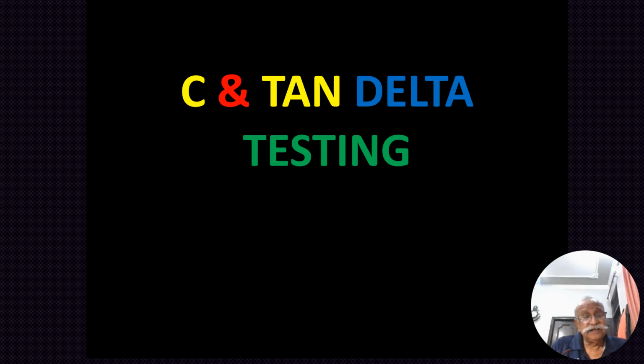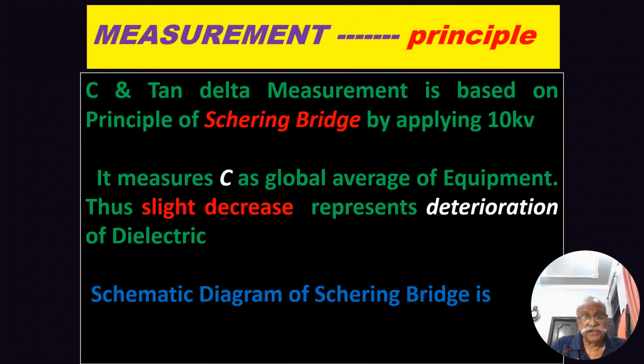Capacitance and tan delta testing. Now we will discuss how to test it. Capacitance and tan delta measurement is based on the principle of the Schering bridge, by applying 10 kV. It measures C as a global average of the equipment. Thus, a slight decrease represents deterioration of the dielectric. And here is the schematic diagram of the Schering bridge.